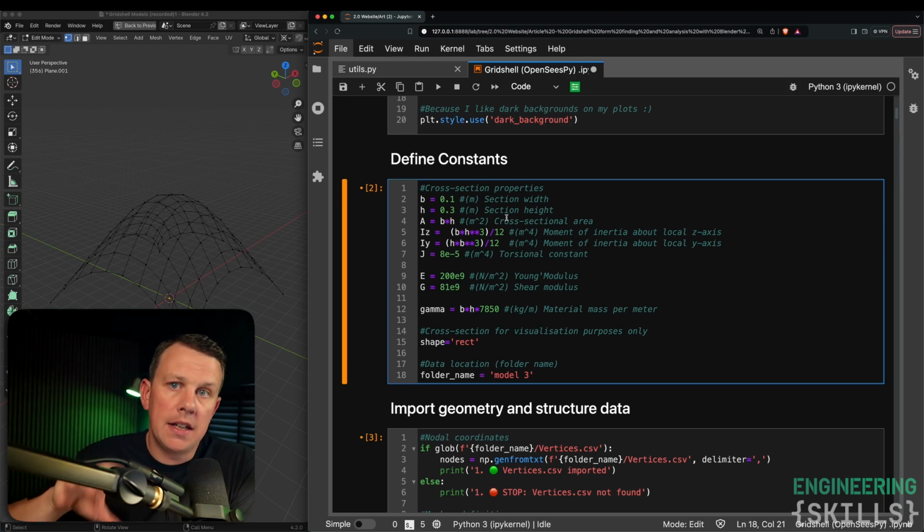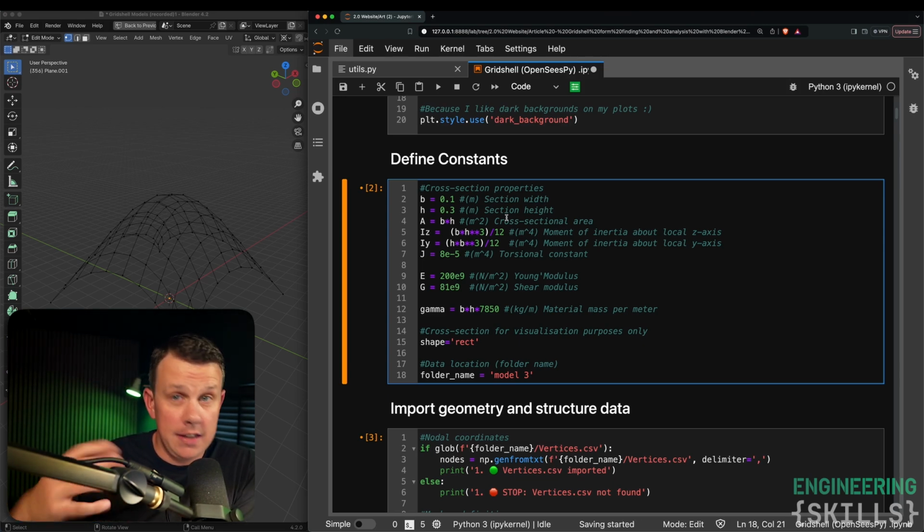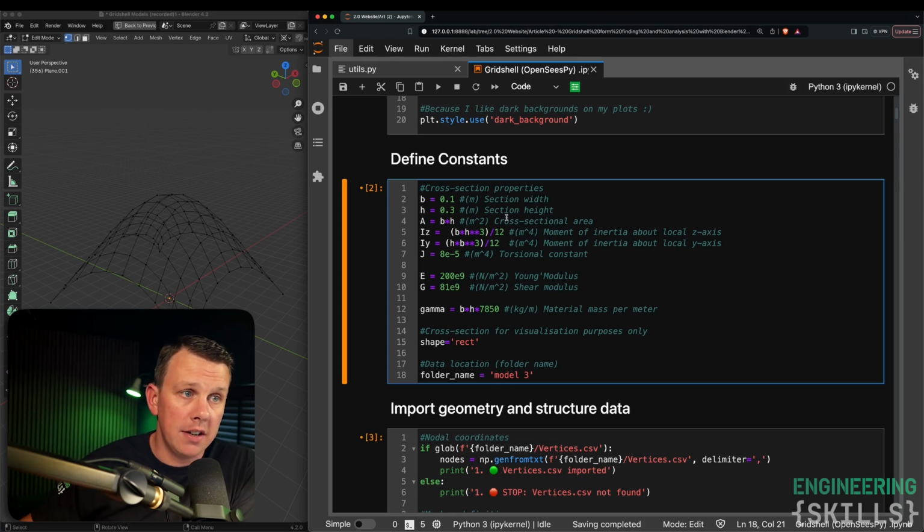Now if you take that structure and you invert it and you lock all the joints, in fact, even if you don't lock all the joints, if you invert it, it should be the case that that structure then goes into pure compression. Because from the structure's point of view, all that has changed is the direction of gravity, right? So all those tensile forces would just flip and become compression forces. Now, in theory, that would mean that, if there's no moments in the structure, we should be able to model it as a 3D truss structure, where all of the joints essentially are pins.